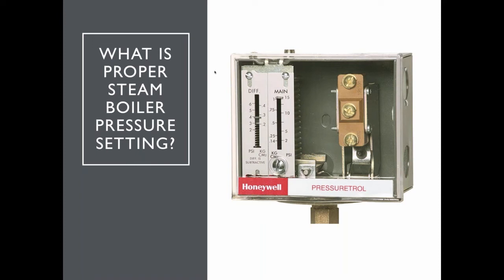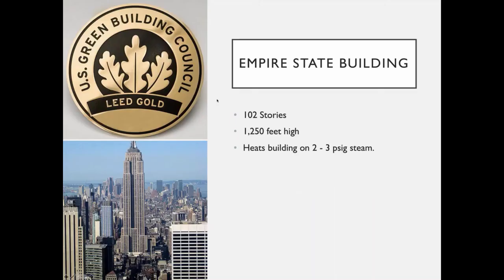boiler pressure is. I hear people tell me, well, one guy, it was pretty innovative. He put a reset control on his steam pressure, and the colder it got, the higher the steam pressure went. But essentially, what you want to do is keep it around 2 to 3 psi, which is what it was designed for. The Empire State Building in New York City, at 102 stories high, won a LEED Gold award. Sorry about that. And they run on steam at 2 to 3 psi.